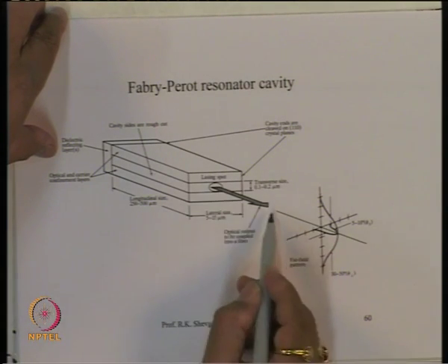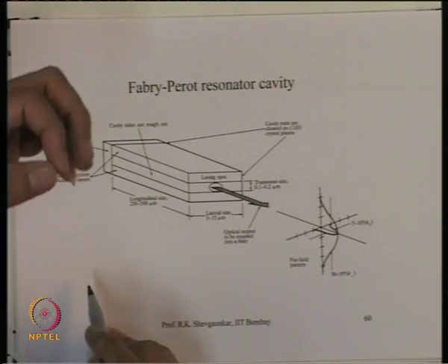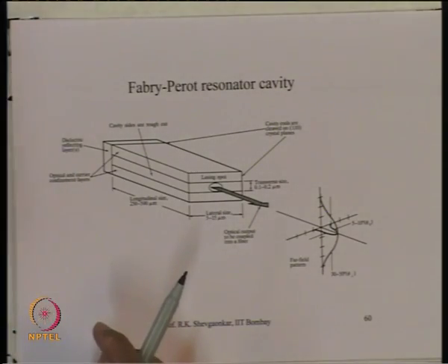So, I can use this mechanism to find whether my laser diode has gone into switching action, into lasing action. So, let us say if I take a laser diode and slowly increase the current inside the laser diode and keep looking at the laser diode at an angle. Before the threshold, since the laser diode works more like an LED, the light comes over a very wide angle. So, you can see the light very dim, but you can see it from a tilted angle from the LED.